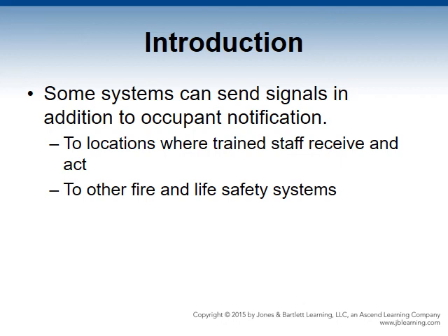They also may send a signal to other fire and life safety systems to initiate other life safety functions, such as capturing elevators, unlocking exit doors, maybe starting fans, closing smoke dampers, and pressurizing stairwells and towers and elevator shafts, so smoke doors, of course, will close and cause places within the structure that are free of smoke so individuals can appropriately evacuate.